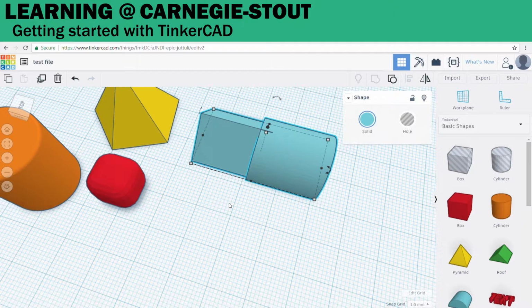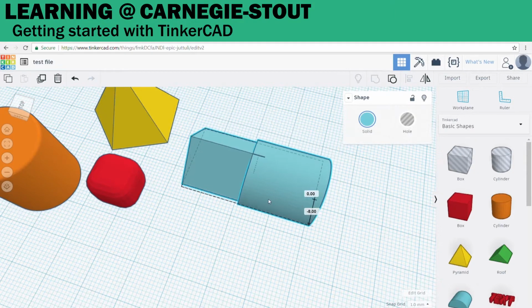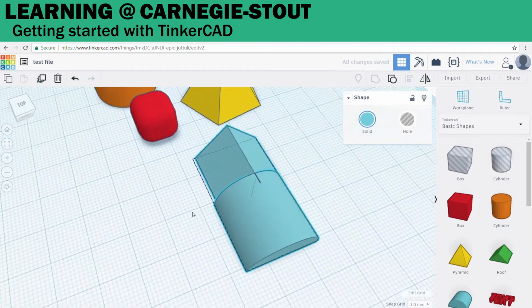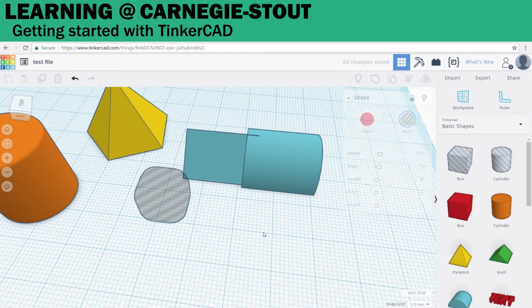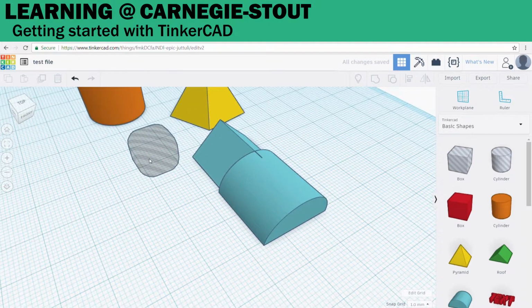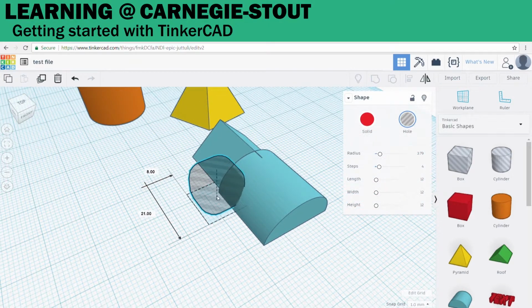There are two basic types of shapes in Tinkercad: solid shapes and hole shapes. Solid shapes are just that. If you were to export this shape and send it to a 3D printer, you would get a printout much like you see. However, if we make this a hole shape, you cannot export that. Hole shapes exist to cut out from solid shapes.